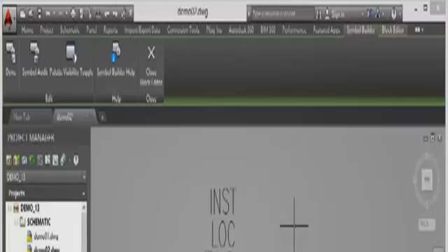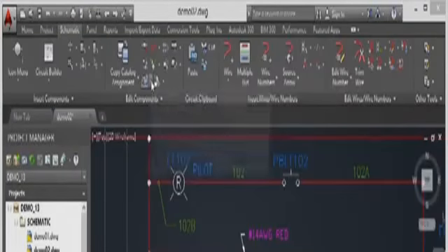So you can see now how AutoCAD Electrical works. When you insert one of these blocks, all of these attributes come in, and all of these attributes are actually linked to the AutoCAD Electrical Project database. So if I now close the block editor without making any changes, nothing will change. But that's how you can add attributes to an existing component, but also create new components with attributes from existing components as well.